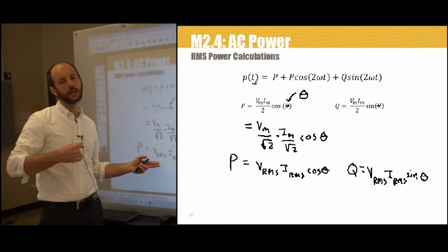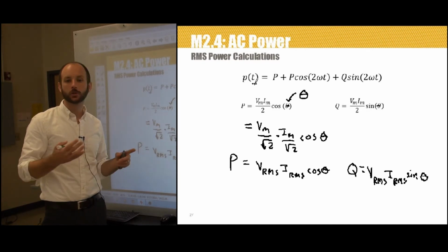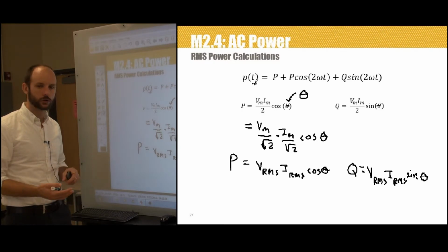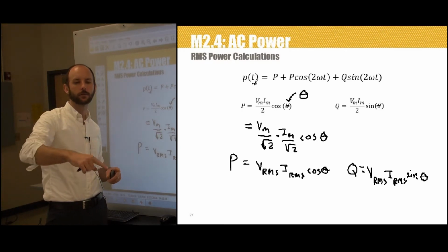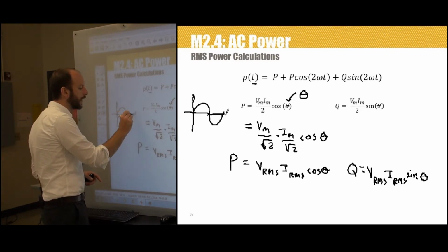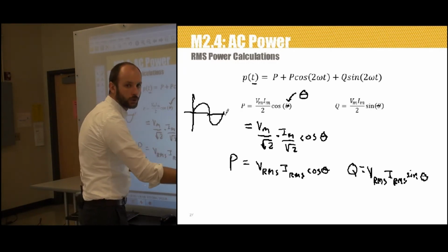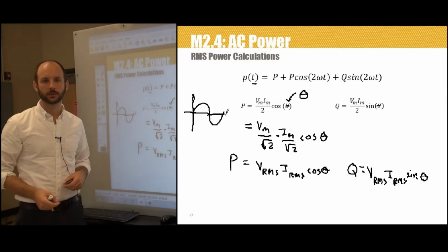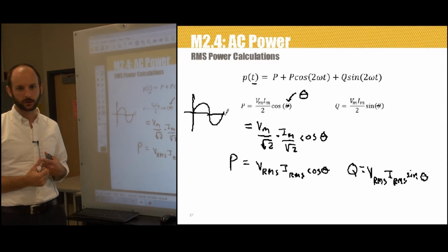That's because in power systems we're mostly interested in time averaged quantities, over the period of one cycle. We want to know what the average behavior is over that one period of the AC cycle, and the quantities that represent that are P and Q. So these are what we end up using in power systems analysis. So we can make some further observations for specific circuit types.